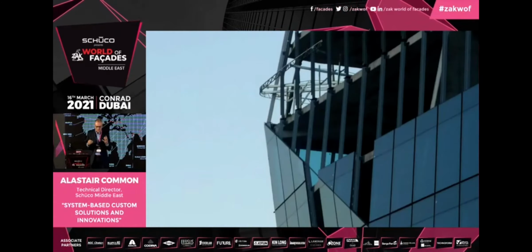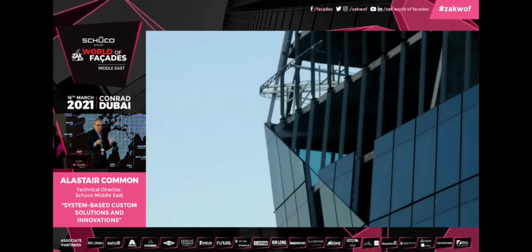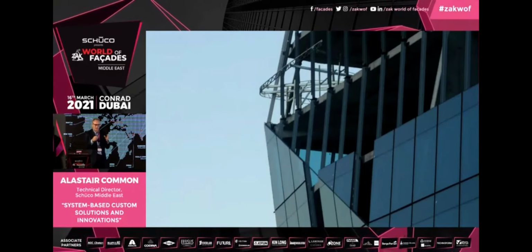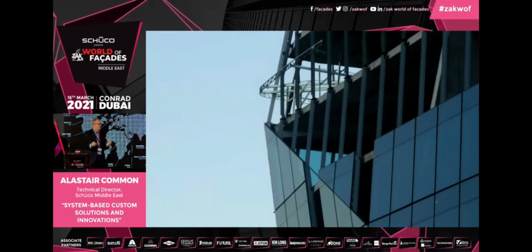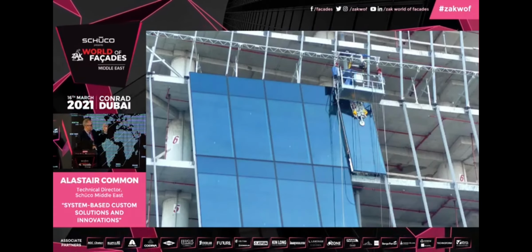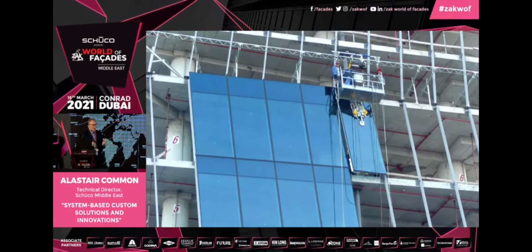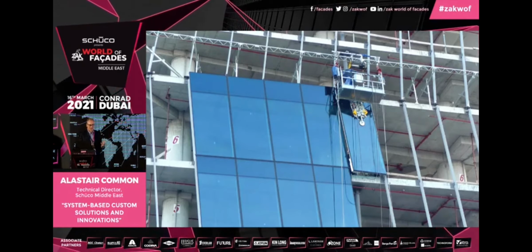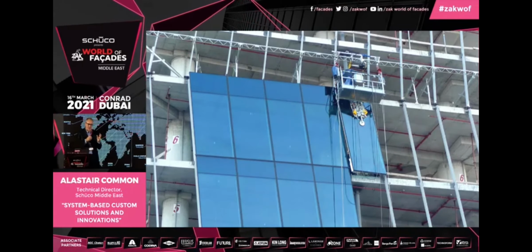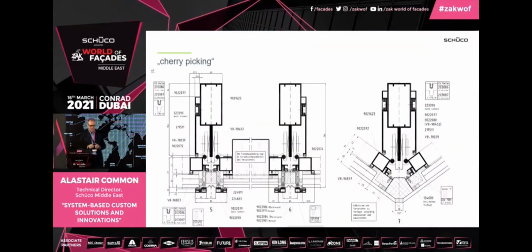So if you look at some of the pictures of the actual installation, you can see the mullions are pre-installed. The panels are all 2D panels, so there is not the complexity of having to think about 3D panel fabrication and design, and you can see it accommodates really well the different geometry. However, one aspect here, which is a problem, is the fact that you do need external access. So whilst this was helping and ticking boxes, at the same time it still needed some addressing.